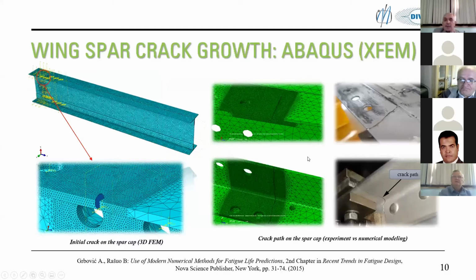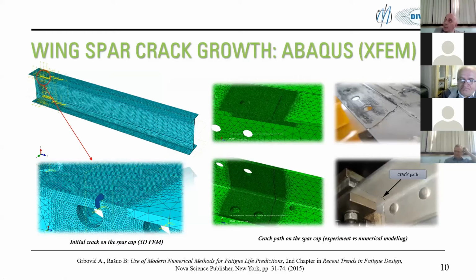And first simulation using XFEM in ABAQUS was on this differential spar. We can see here on these images that the crack path that we obtained in these simulations was almost the same as the crack path in the experiment. And that was the evidence that all these boundary conditions and all the other things,